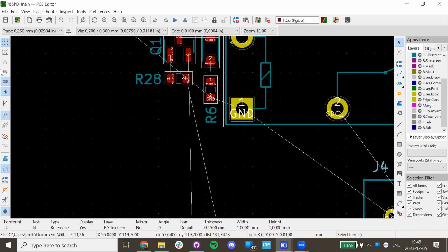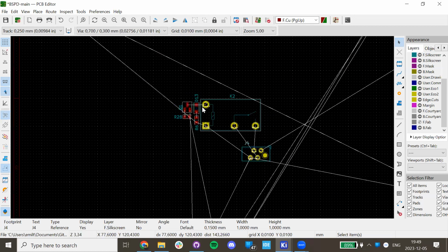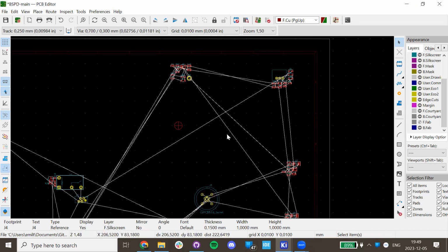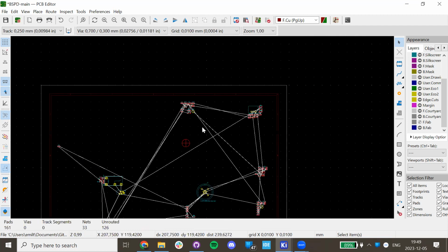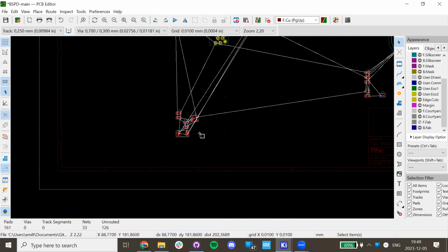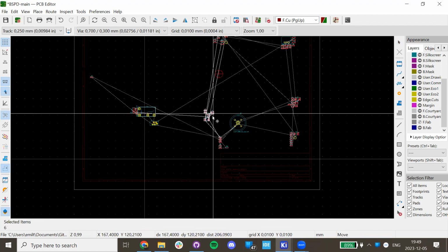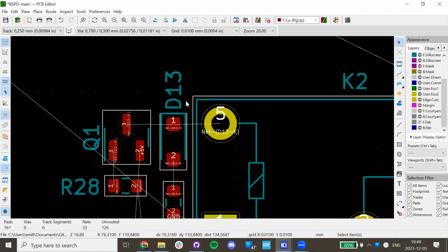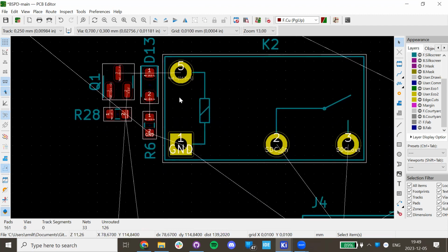But it's good to do this kind of thing. I started with placing everything in one block. It's one way to do it, but now I placed all of this in one end. I know this all belongs together. This needs to be close. And then I can take this block and place it far away. And this DC-DC, for example, will be noisy. They can be pretty close together probably. But then the analog stuff, as Tore said, I can place it on the other side of the PCB here. Okay, but I like to route locally here actually, because then I can easily spot issues.